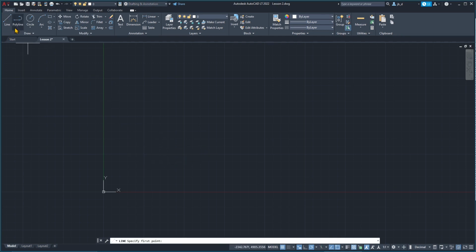So for example, if I create again a really simple line, click there, it's going to show me a length. So it's going to show me numbers. What does that number mean? What does 1087 mean? It means that we are approximately creating a line that's 1 meter long. So 1000 millimeters equals 1 meter. So the basic units of AutoCAD, unless you change it, are millimeters. So every time you create something in AutoCAD, it's going to be in millimeters.